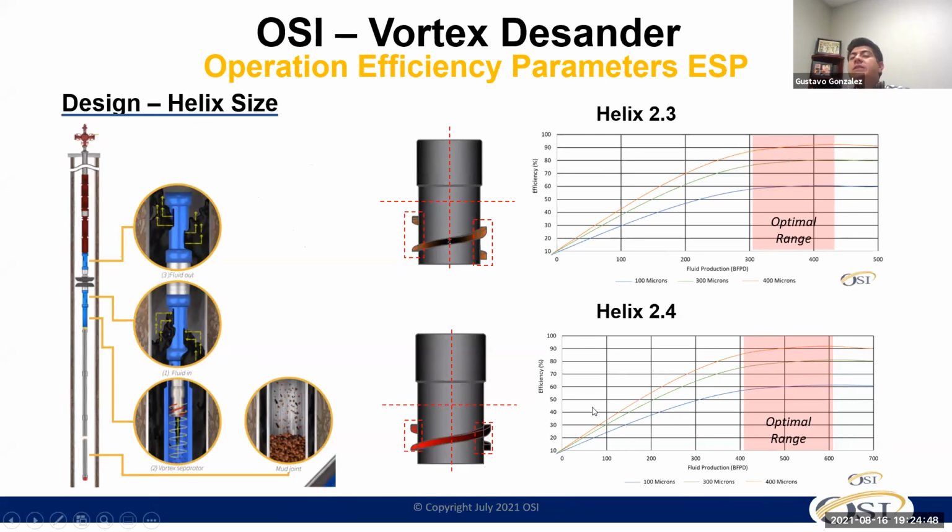And that's why we always use this in correlation with the rod pump, because every time we change the pumping unit from a conventional to a Rotaflex or any hydraulic system, where we increase the stroke length from 198 to 320, because maybe we have gas as well and we want a longer stroke and lower pumping speed to deal with the gas, that's great. But that delta P is changing at the bottom, and we have to be sure we give the right helix and get the right force to spin those solids and particles out and generate the filtration or separation that the customer was looking for.